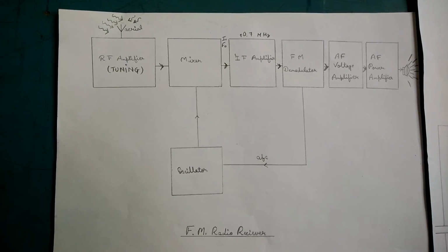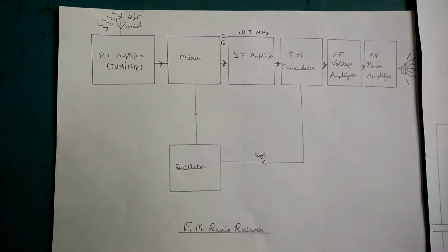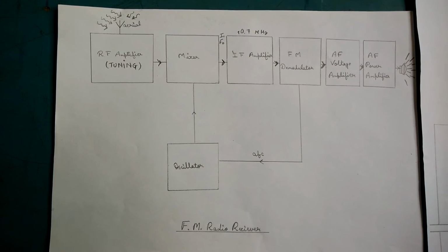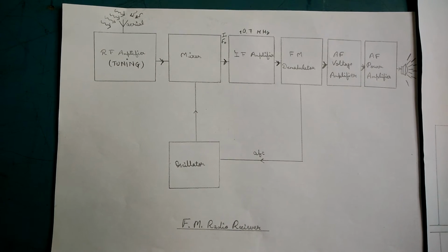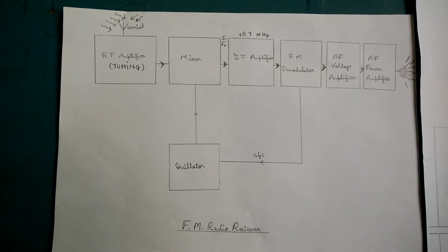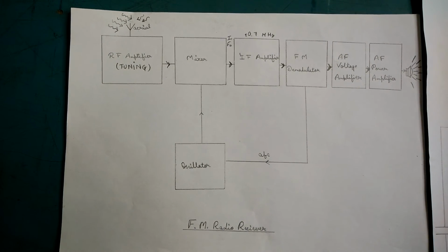Effectively, we have the channel through which the FM information is transmitted. Our radio picks up via the antenna all of that information. There is a mechanism through which we tune a filter that selects only the desired frequencies and all others are blocked. Amplification ensues and it drives our speakers.